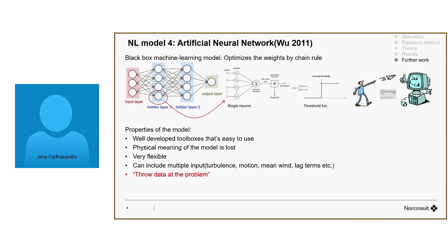Yeah, the way that we are thinking about training this neural network is you get turbulence, or basically wind pressure on the cross section, as input, and the motion of the cross section as input, and then the force is output. So it's actually independent of the dynamic system of the cross section, as long as we have calibrated the model to include different kinds of motions. As long as the motion from the floating bridge is inside our validation area, it doesn't matter. So it doesn't matter what the actual damping of the system is.